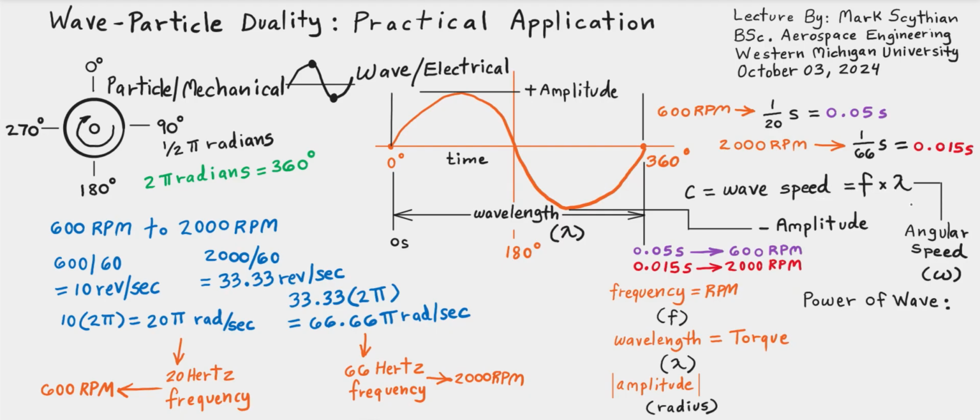And this translates to the angular speed, or the circular speed. So if we took pi d, circumference, and then we multiplied it times the number of revolutions per second, we can get the circular velocity with respect to pi d times revolutions per second. That would just be the speed of this wave going through. And so that could be translated to the transmission and/or the linear travel. So every time you rotate this wheel, it's pi times d, the diameter times pi, and that's how much linear distance you would get on the road.